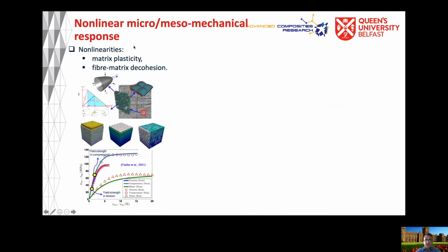I also work on the nonlinear micro-meso mechanical response of FRP composites. So if you consider FRP composites, on the micro level, this is the representative volume element. So we have matrix and fibers. So again, I include matrix plasticity, and I also include fiber matrix decohesion.